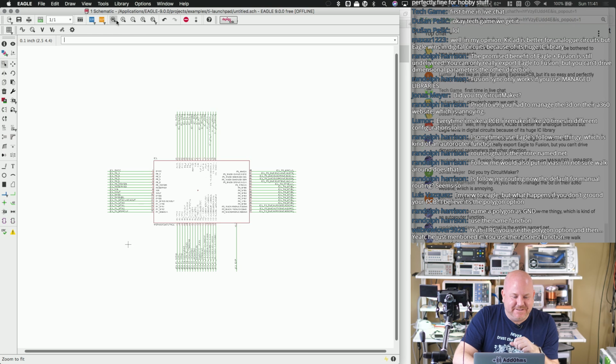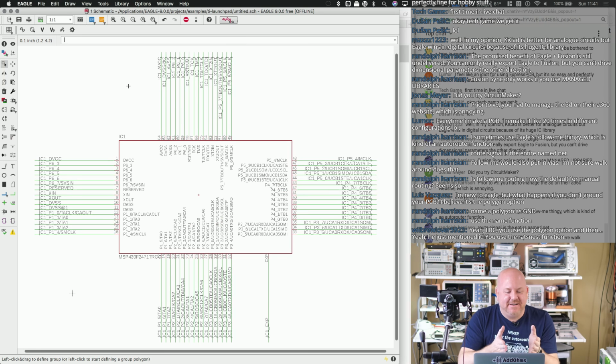I absolutely love that. Being able to get all of my IC pins broken out, they're named. Maybe the names aren't what you're used to using, so okay, you got a little bit of a hiccup there, but I really enjoy the idea that I could go create my own symbol, name the pins the way I want. That would create my nodes around the schematic the way I want.